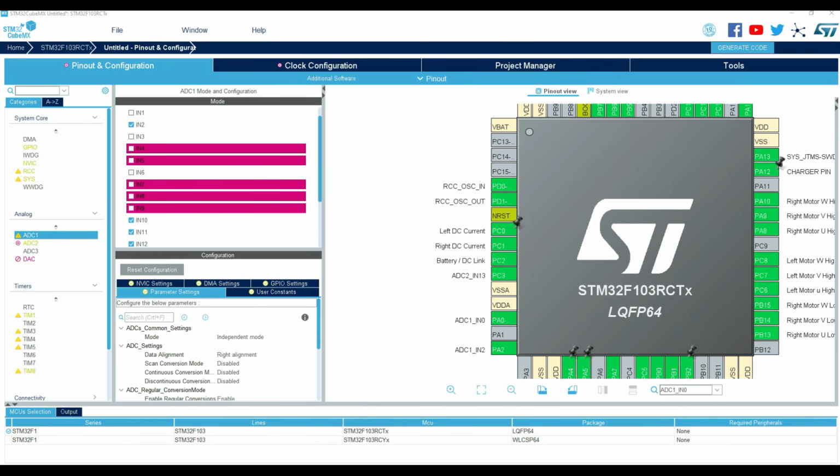If I go into more detail, it is for battery voltage protection. If voltage is 42, it stops the motor to prevent destruction. If the voltage is lower, around 30 volt, then power is reduced, so the battery won't deep discharge.